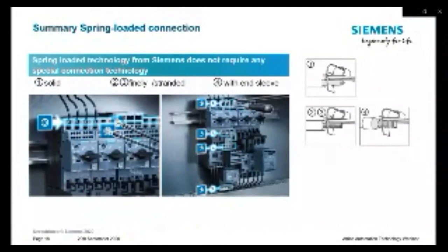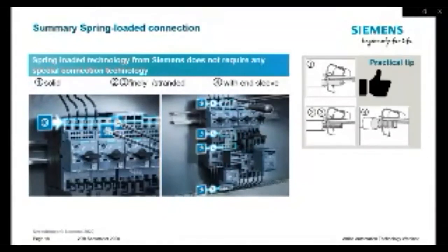provide many advantages. I already mentioned that spring-loaded technology from Siemens does not require any specific connection technology. They can be used with solid, finely stranded or stranded conductors, or with or without end sleeves. So it does not matter at all whether you use sleeves or you don't, and which conductor you are going to use. Well, it's one of those practical tips I would give you in addition.